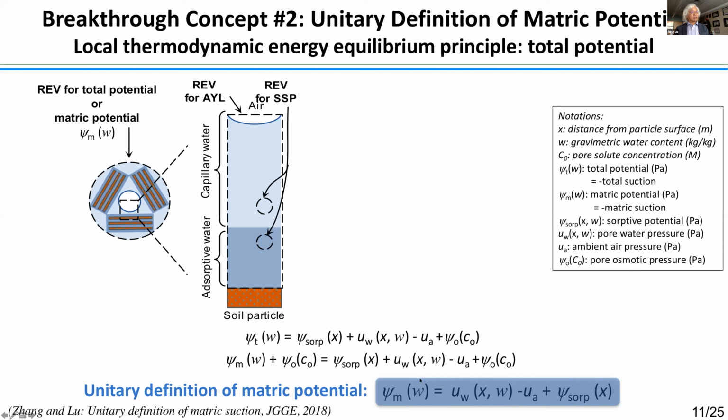In fact, it is interesting to look at the terminology, because when we first defined matrix suction, we thought that it is due to the soil particle, which is true. However, the equilibrium condition we are always looking at is whether the air humidity, or what we call the suction environment. So in fact, this is the relation that we can completely unify, and it has two components.